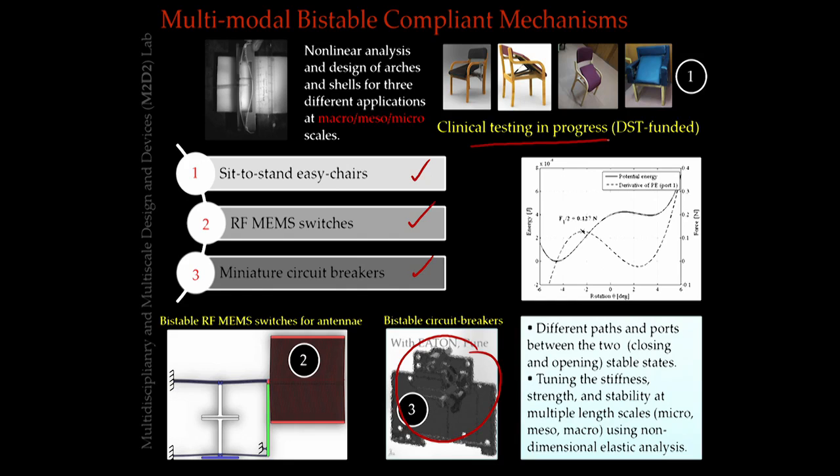So, the bistable phenomenon, again to summarize, needs to have an elastic element that stores energy, stores energy to the maximum during the travel, and then it decreases. So, state energy should increase and then decrease. If that is the feature, it will have bistability.